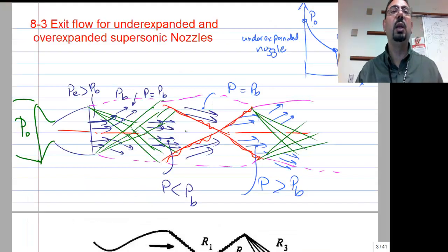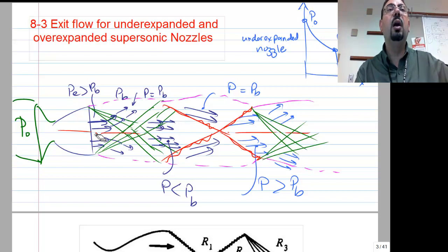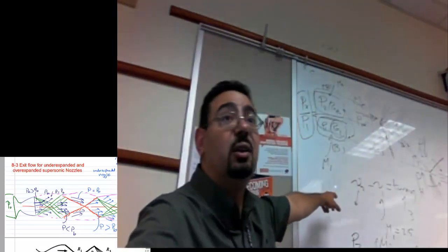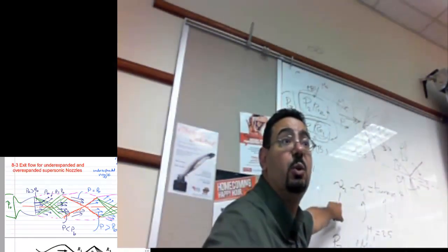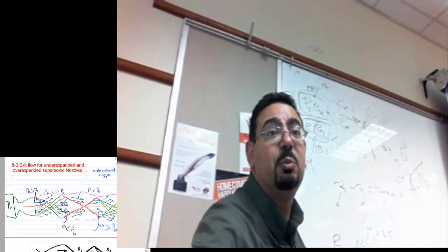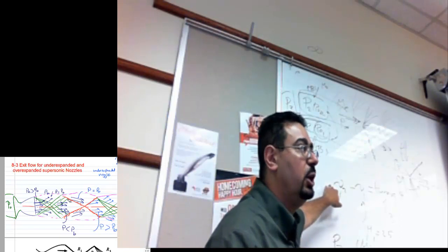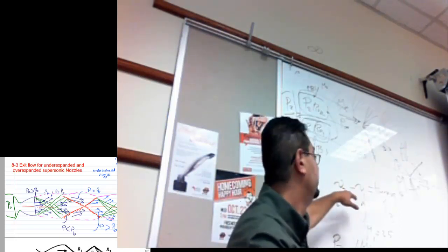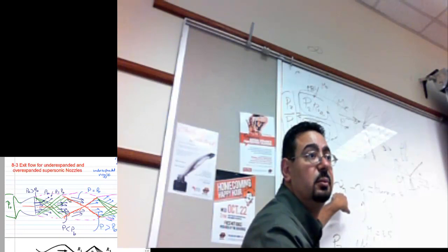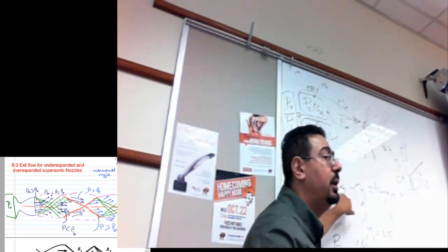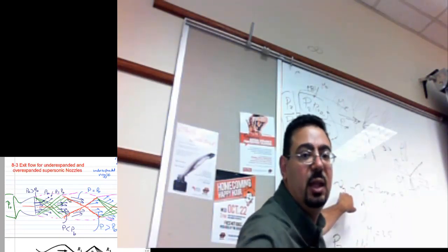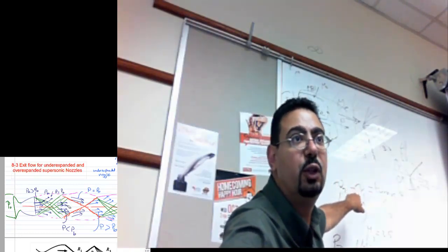So what happened? He straightened up, and how much? If I want to solve the pressure over here, I want to know how low it will get. How am I going to do this? The one and only equation. I don't have anything else when it comes to expansion. I have to use this equation. So if I'm asking you to give me that pressure here, and I'm telling you to use this equation, what do you know? Obviously, you don't know the Mach number after the expansion fan.